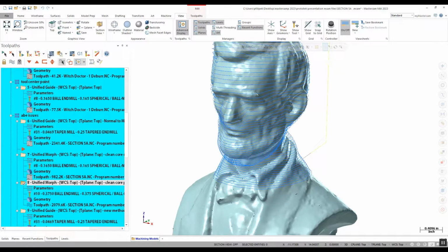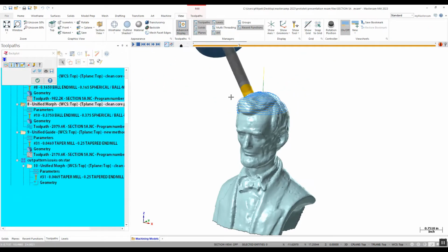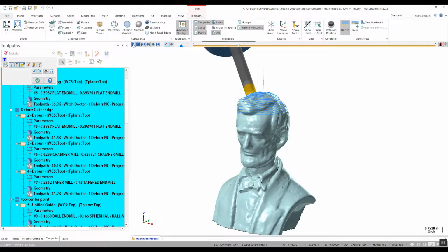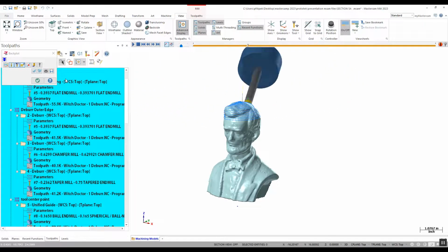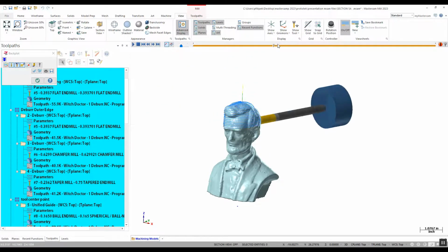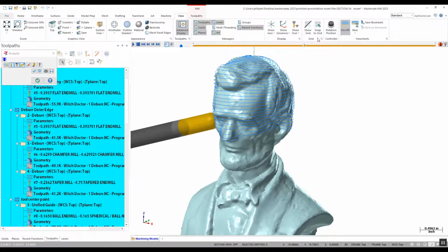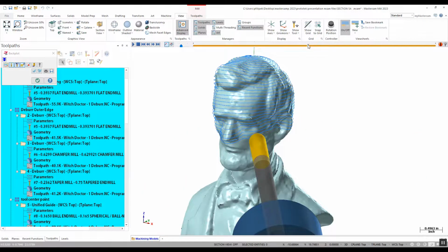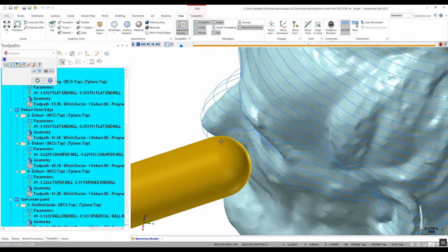So when we do this, it looks a lot better. I'm getting pretty decent tool motion. I got a zigzag on, but you can see that it's just back and forth. Pretty decent motion, right? The motion is pretty nice, but where I lost out is on pattern. Specifically when I get down into these areas here, it can potentially not be the greatest pattern that I want. Maybe I don't want to cut with my ball end mill there. Maybe it's going to cut more on the top or the back side of that ball end mill. So I compromised cut pattern in this case, but I smoothed out the tool path.